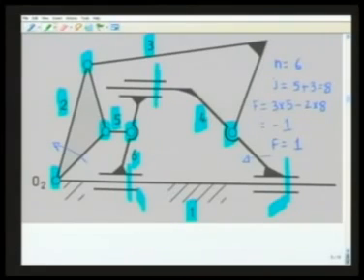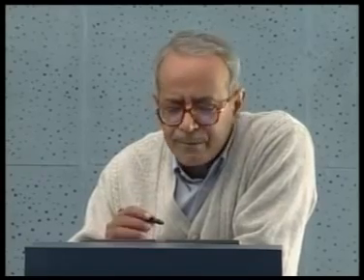So this prismatic pair, which is there to ensure horizontal translation between link 4 and link 6, may be redundant. Even we can withdraw any of these 3 prismatic pairs because all of these are ensuring horizontal translation between links 1, 4 and 6.